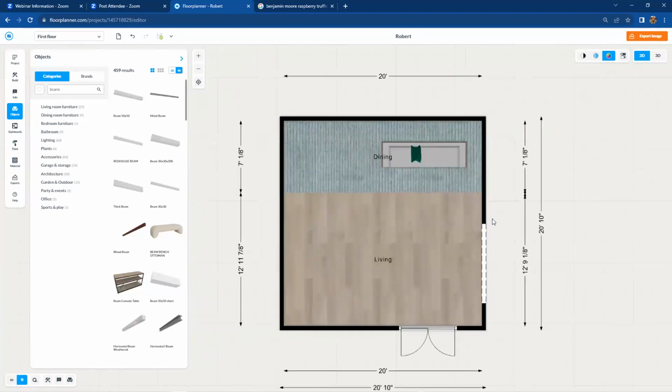So at least get those structural walls and load-bearing columns above and below each other. Then if you need to change the partitions on the second floor, you can always delete the other peripheral walls and redraft the correct walls as partitions, but leave your load-bearing and structural elements in place.